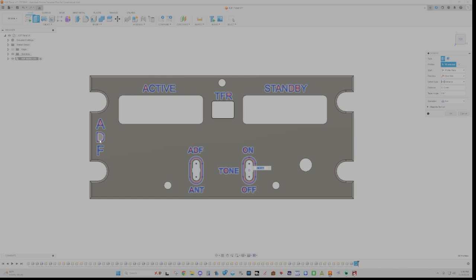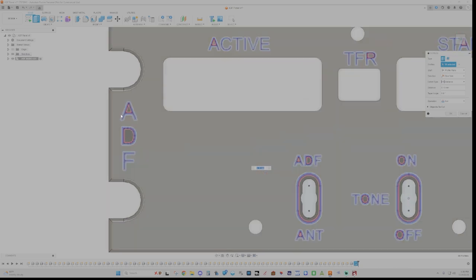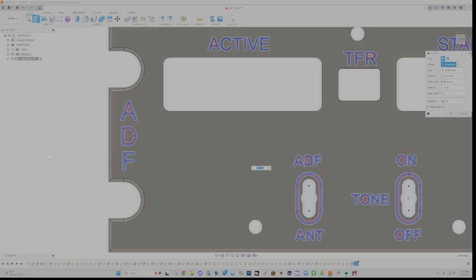You'll see in the void spaces here, like on the A, the D, the R, the O, the inside circle is red. That means that the area inside the red area is not selected. So the easiest way to do this is to come over here, on that bottom here, we're going to go join, and then for extent type, we're going to go from distance, we're going to go ahead and do it to object.